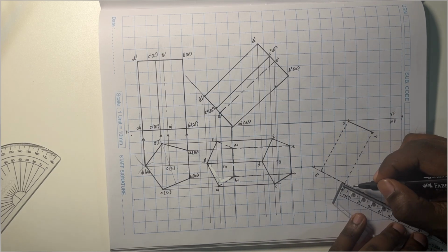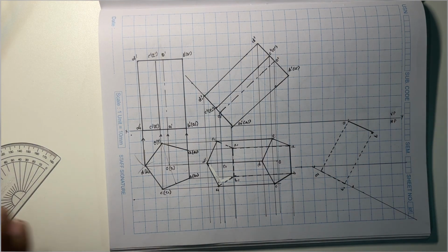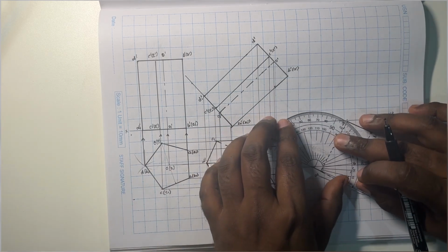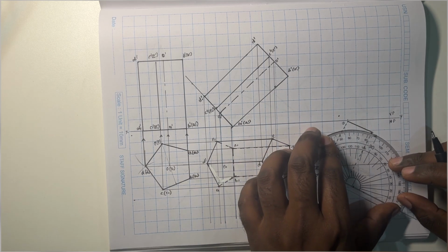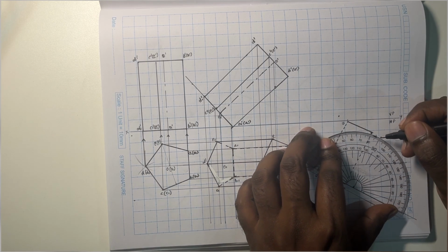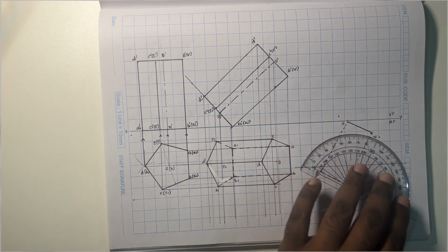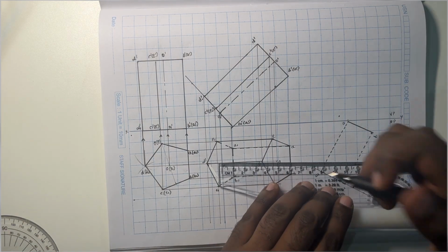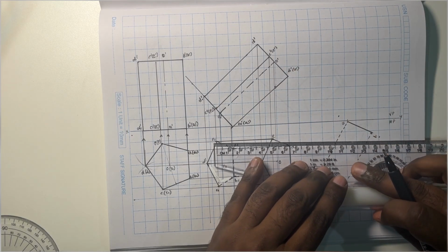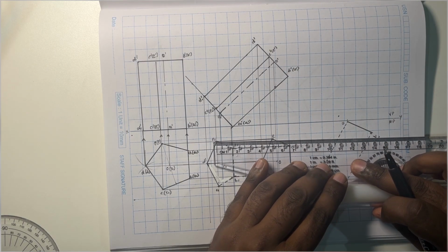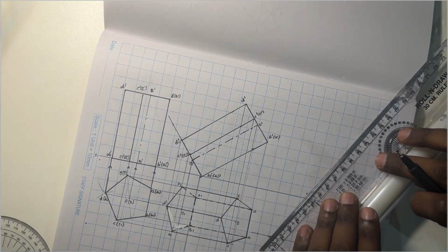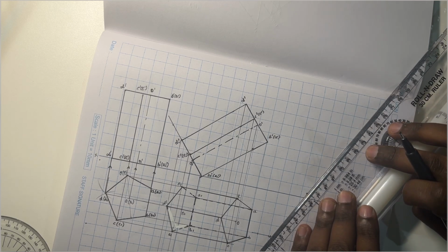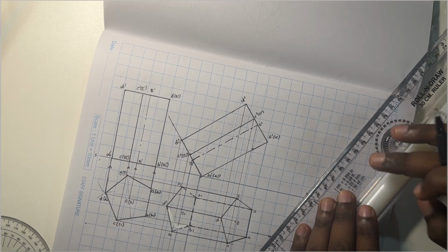So I'm going to mark these points, and again from here I'll be drawing this 90-degree line. So I'll mark 90 degrees and then 90 degrees here from this marked point. So now I'll take the measurement from this particular point. E1 is at a distance of 1.9 mm. So I'll mark a point at 1.9 mm with reference to that 90-degree point. So 1.9.